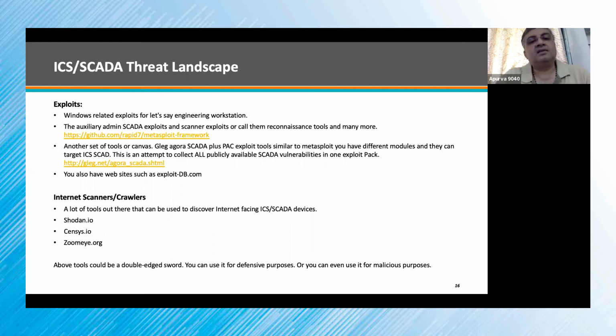What it does is it attempts to collect all the publicly available SCADA vulnerabilities. There are CVE sites and others where the OEMs have published the vulnerabilities in the SCADA system, for which firmware and which version. So these are available. This tool collects all of this, and then it will try to exploit them based on the type of system that you have.